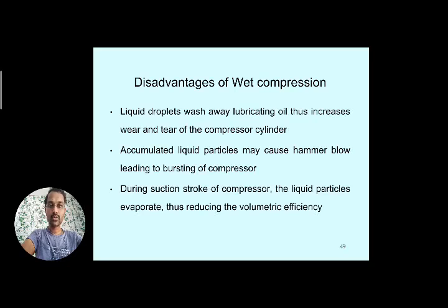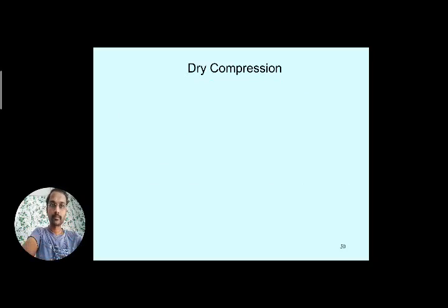And during the suction stroke of the compressor, liquid particles evaporate. This is also one problem. They evaporate during the suction stroke of the compressor, thus reducing the volumetric efficiency.